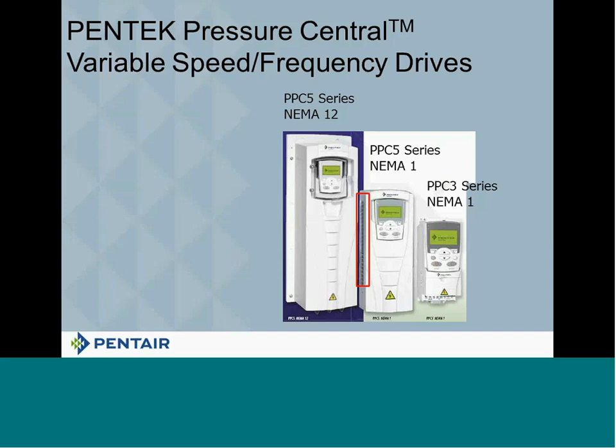What those slots do is they allow for the drive to breathe, which means this needs to be used in a room that's not very dirty. If you've got a room that's very dusty, now you want to use the PPC5 NEMA 12, because the NEMA 12, as you'll notice, has no vents. The only opening for air to get into there is at the bottom. And there is a filter there, and it filters all the air that gets pulled through.